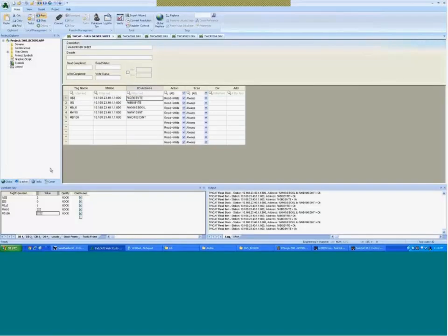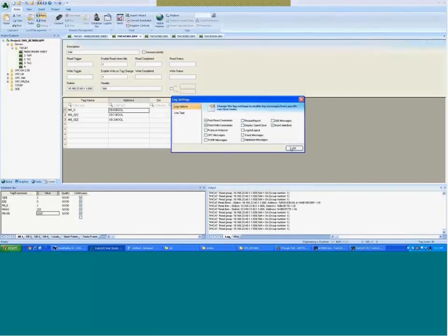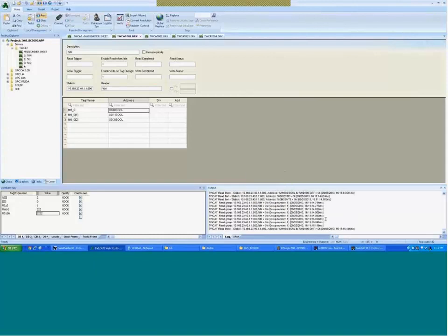So if you're configuring standard driver sheets for this, you're going to have a standard driver sheet for the M's, a standard driver sheet for the I's, one for the Q's, and so on and so forth. All right, so if I go here on my M's and I enable the communication, they're going to be pretty fast again, as you can see here on the right side. If I pause, we have again around 30 milliseconds for every communication. Again, because we're talking to the ADS, I'm not going directly to the PLC. I'm talking to the ADS, and the ADS is doing its magic, acquiring the data at the speed of light and just giving it to me whenever I want it.